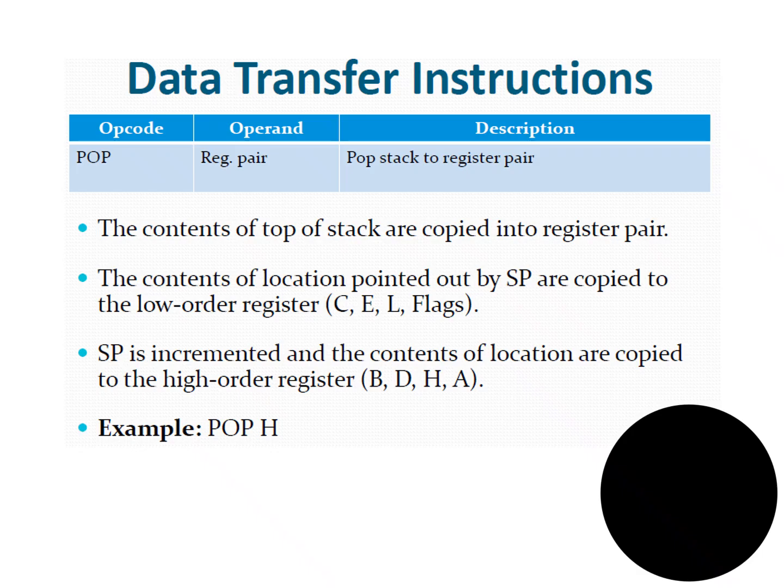During the pop operation, the stack pointer will be incremented because we are taking out the data. When you push into it, we are lowering into the stack, so the stack pointer will be decremented.